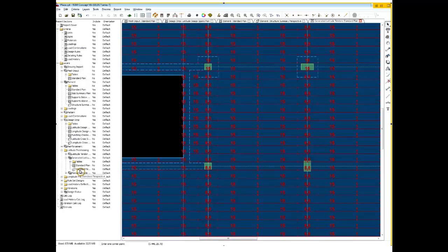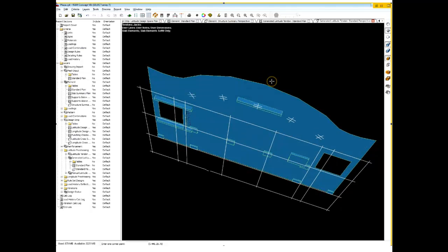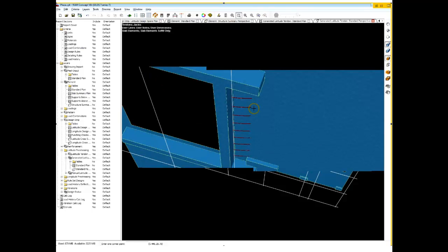Each tendon layer has a perspective, both in the generated and in the manual layers. And so with this perspective, it's much easier to see those issues. Now, maybe not so much from the top, although it could be sticking out of the surface. I have by default the soffit on here, so I'll just rotate this around, and I'm going to zoom in. Let's get it into a good spot. All right, so there's the problem right there.